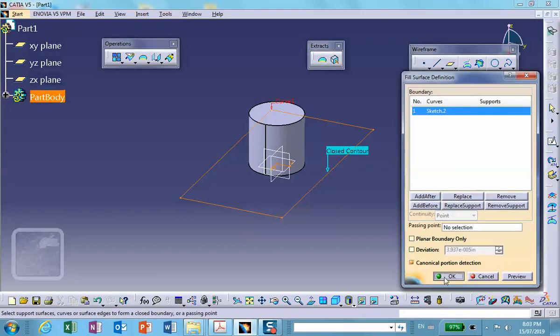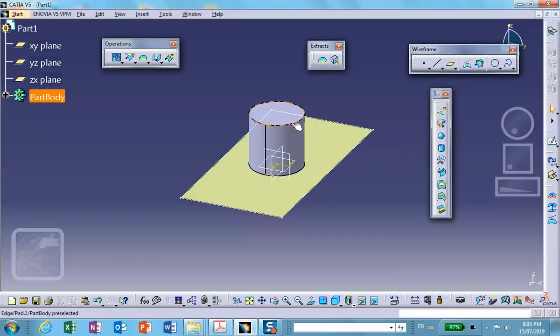There we are. And now we have to make a decision on whether we want to make a hole here and then connect the surface of this cylinder with the edge of that hole, or we can just leave it like this and pretend that the bottom of the cylinder was glued or fastened or welded, surface welded to that surface.